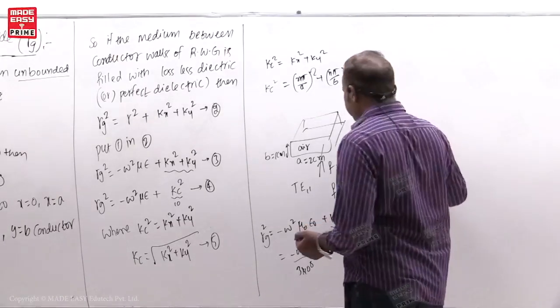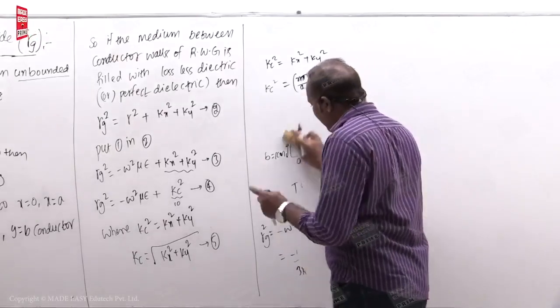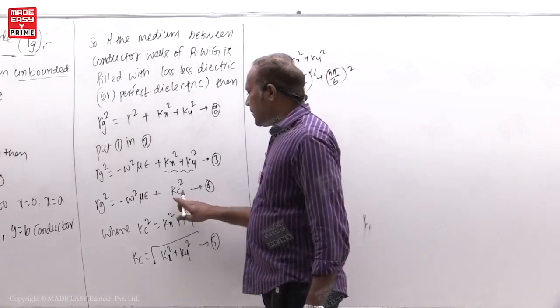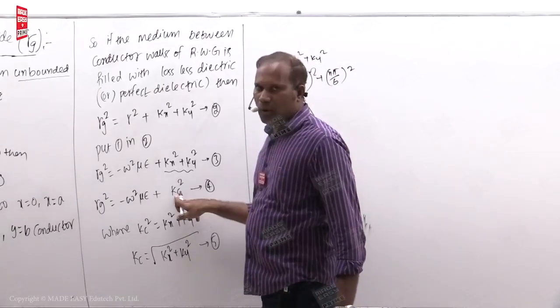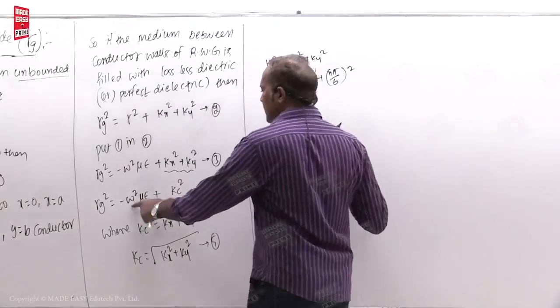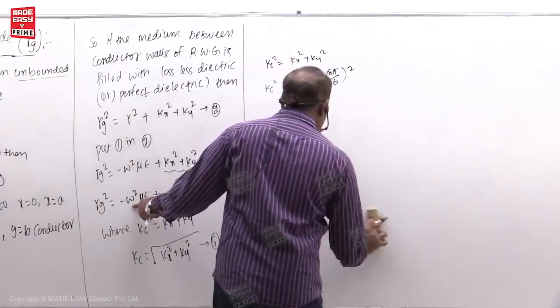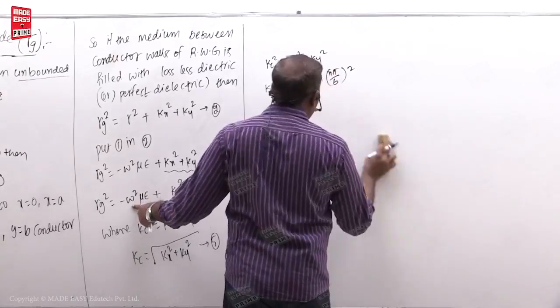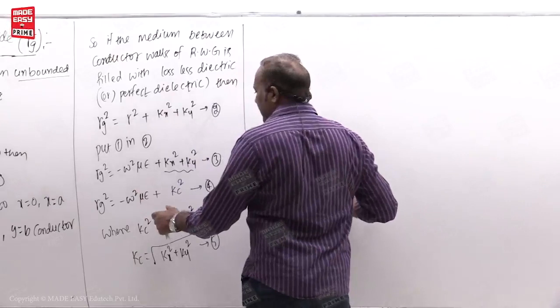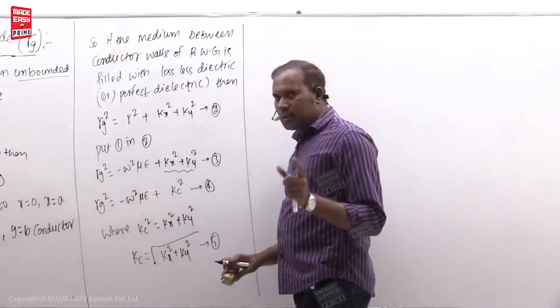So dear students, what I am telling you, till now what I have explained, for a waveguide this is constant for a particular mode, and this is also constant, this is variable. Keep changing this f in such a way that at a particular frequency, called f is equal to fc, or otherwise omega is equal to omega c, this gamma g becomes 0.